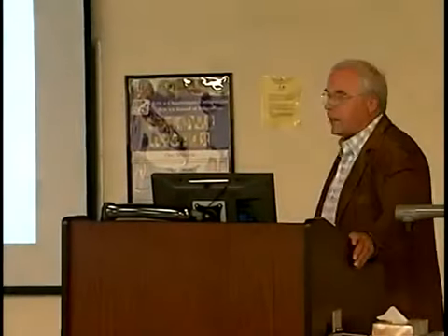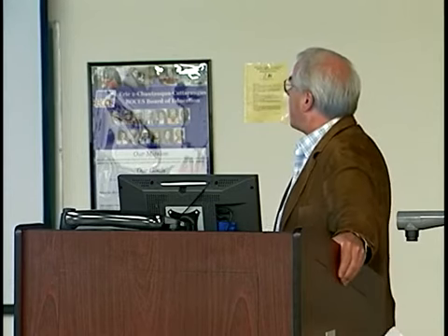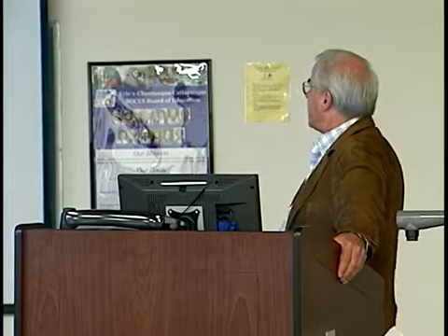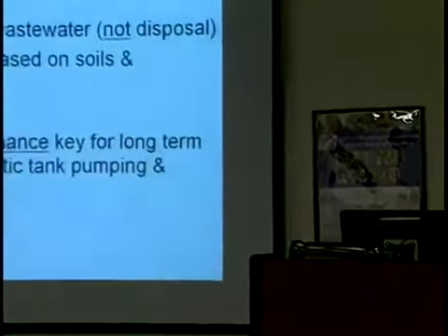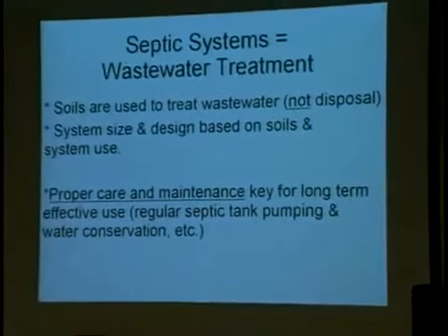Now, on-site wastewater treatment, conventional and alternative. You've heard a lot of things here today about it. What we know is soils are used to treat the wastewater, not dispose of it. I do not refer to an on-site wastewater system or septic system as a disposal system. You hear that a lot. They are an on-site wastewater treatment system. The system size and design is based on soils and system use. Proper care and maintenance is key for long-term effective use of these systems. Regular septic tank pumping and water conservation.